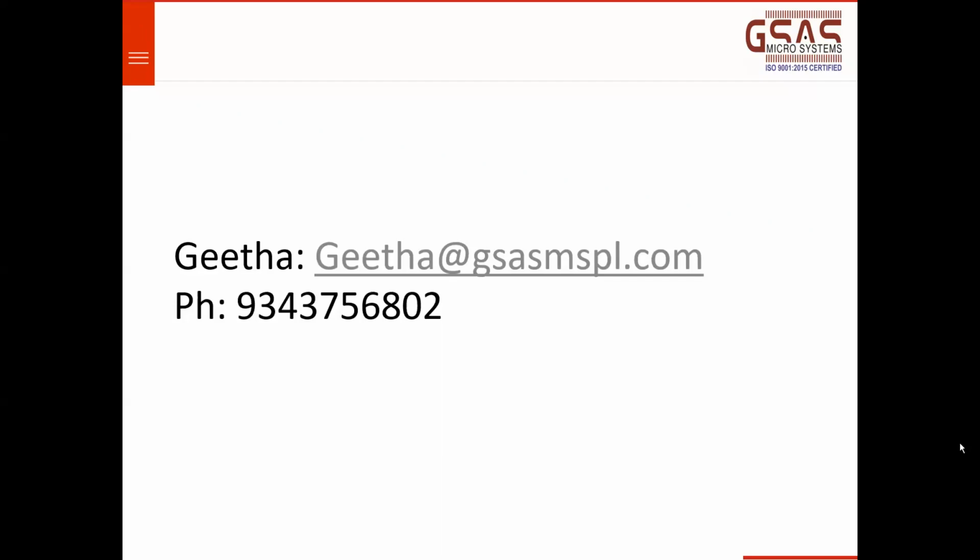As per this VTU syllabus, if they are asking for version 5.0 plus, then that is not the solution, because version 5, or whatever the latest demo version available on the Keil site, doesn't support ARM7, ARM9. Because you want ARM7, please continue to use 4.74.